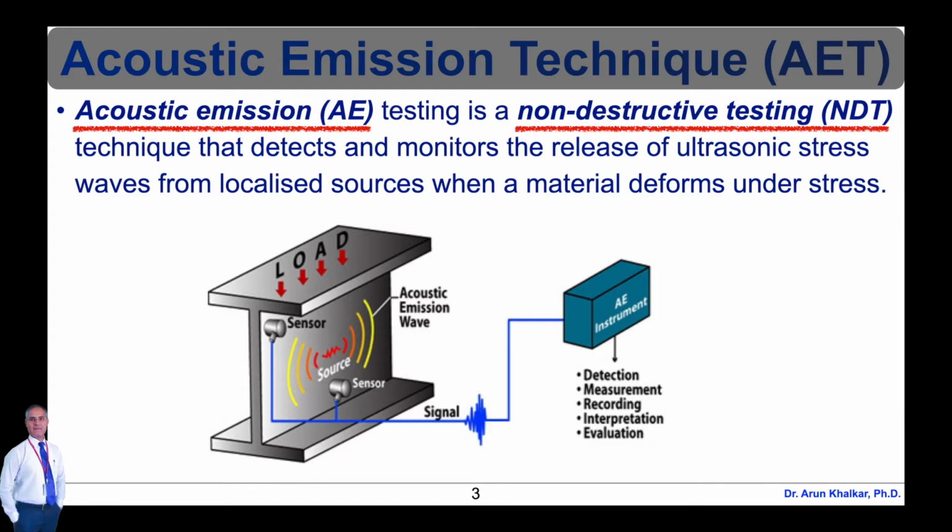As the damage grows in the component, there is a greater release of energy. The rate at which the acoustic emission is detected, the activity, and the intensity of the acoustic emission, the loudness, are monitored and used for assessing structural integrity and for health monitoring of components.